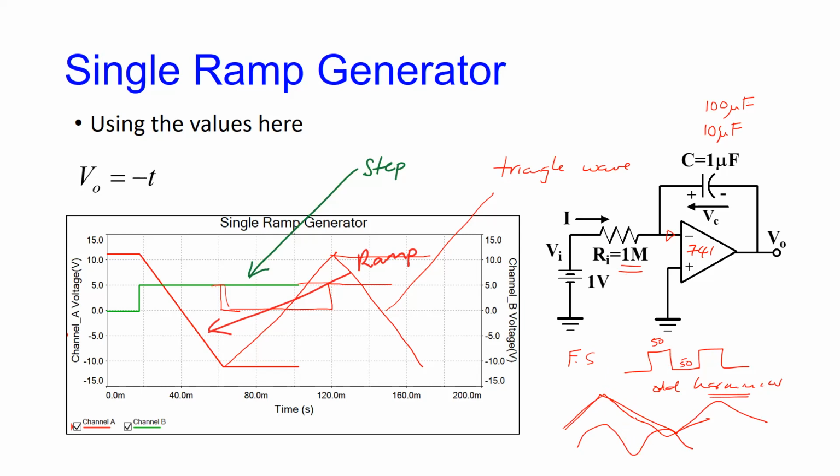You remember one of the things that we said with things like the Wien bridge and so on is that the Wien bridge and the phase shift networks have a set of equal resistors and capacitors. And if you want to change the frequency, you have to change either all the capacitors together or all the resistors together. Or in the Wien bridge, there were two.